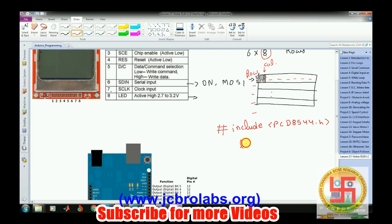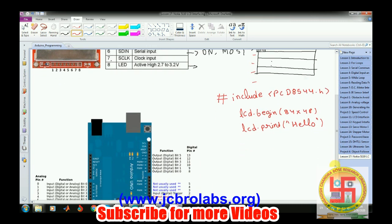First of all, we need to write lcd.begin in order to initialize the LCD in this 84 cross 48 mode, and then there is another command like lcd.print. So if we want to print any string, then that can be printed directly like this. Okay, so these are the functions which we'll be dealing with when we write a program.